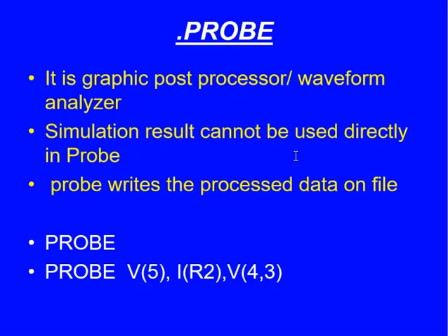That means before the probe command, we need an analysis command. The syntax of the .probe command is .probe followed by the different variables.